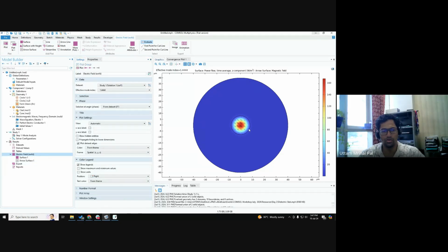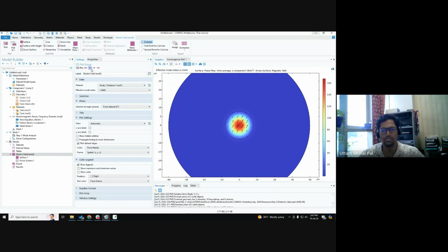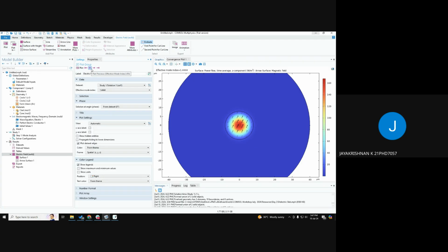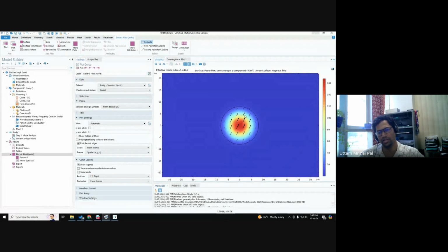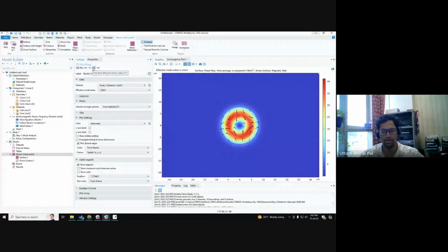What you see over here are the hybrid modes. There is one course on NPTEL by a professor at IIT Madras, I don't remember, Professor Balaji. Balaji Srinivasan, sir? Yeah, or Balaji, IIT Kanpur professor. I don't remember exactly, but there are nice notes as well. In his notes he mentions all these directions, and they correlate to particular modes. If you do a Google search, you will get that. All these modes are either hybrid modes or LP MN modes, some of the linearly polarized modes.